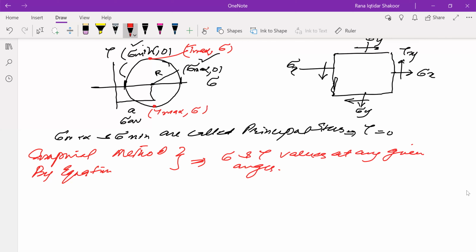In this specific chapter, now we are cutting this section in this way or in this way at any particular angle, and we are saying that these are basically the x prime and y prime. This is obviously not perpendicular to this one. It should be perpendicular, but this is now perpendicular, so this is y prime. So x prime, y prime. These are at angular orientation to the x and y plane, because initially this was the x plane and this was the y plane, right?